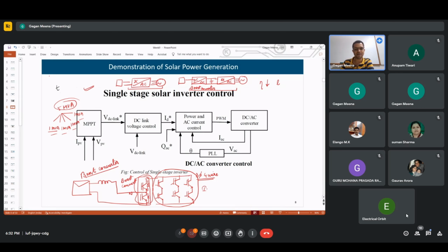In mode 3, the control box is not in the cable, it is outside, inside an equipment which is the electric vehicle supply equipment, and it is permanently connected to the network or the grid. These are wall mounted or commercial automatic charging stations. They have all these features, and the safety feature is inside the EVSE equipment.